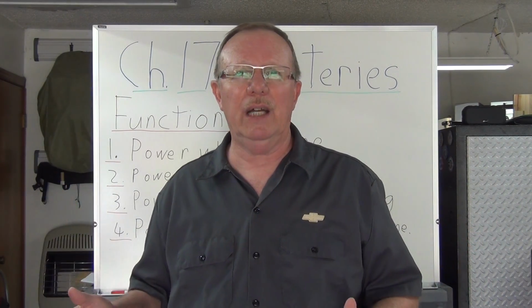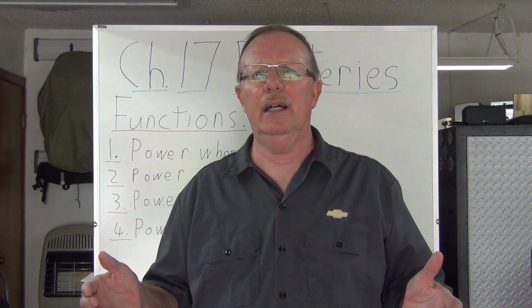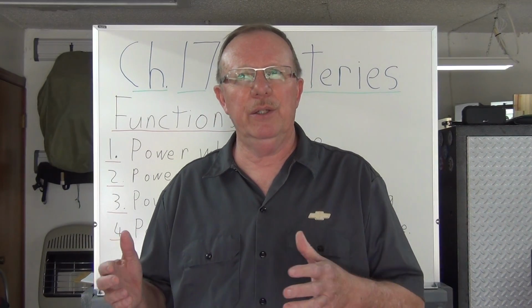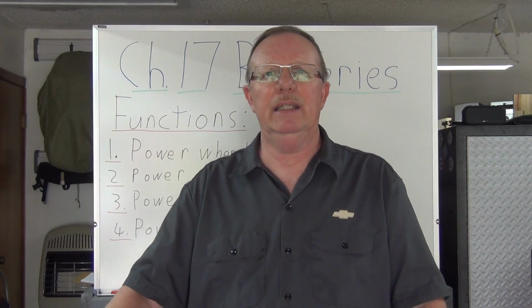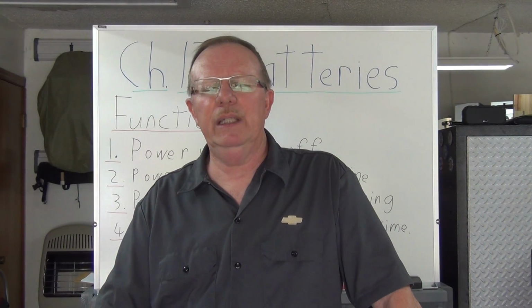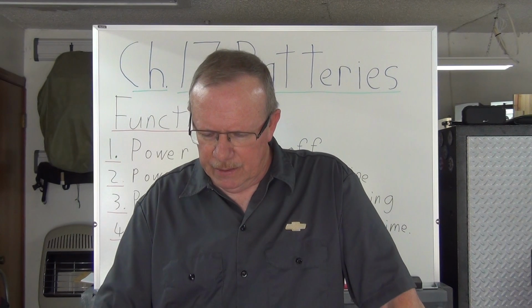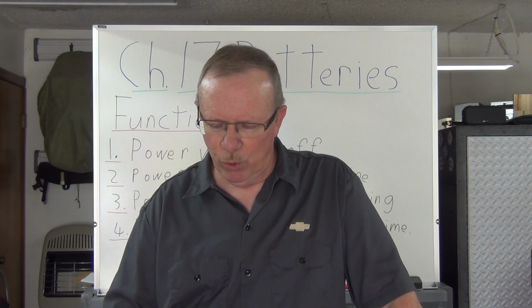They parked it, didn't drive it, or maybe they just drove it a couple of little short distances, and then the battery's dead in 6 months, right? So after I put that new battery in there and I took the time to charge it for an hour and a half and test it again, we didn't have any more trouble with that particular van. So there are cases like that where that makes a difference. Okay, another tip there that might be important.